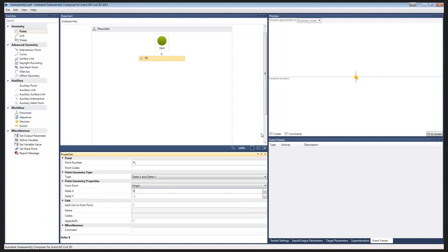So I could actually say, drop this down 2 feet because I got 6 inches of blacktop, I have 6 inches of rock, and I have a foot of sand. And I could build my surface just based off of this. Well, we're building curb, so we want to leave this at 0 and 0.